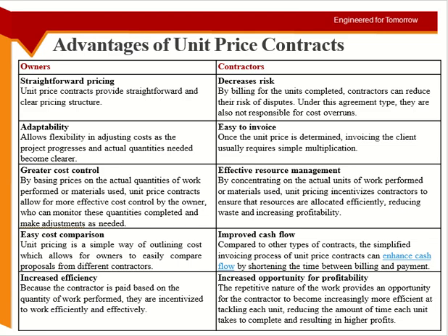Okay, and some contractors become smart as well. So what they do, they know they need more money at the start, right? They need more money at the start. So the start items have more margin in them. And on the middle and the end items, they reduce the margin. Okay, so for the client, the overall cost may still look reasonable. But the contractor is improving his cash flow. Okay, so this is also being done.